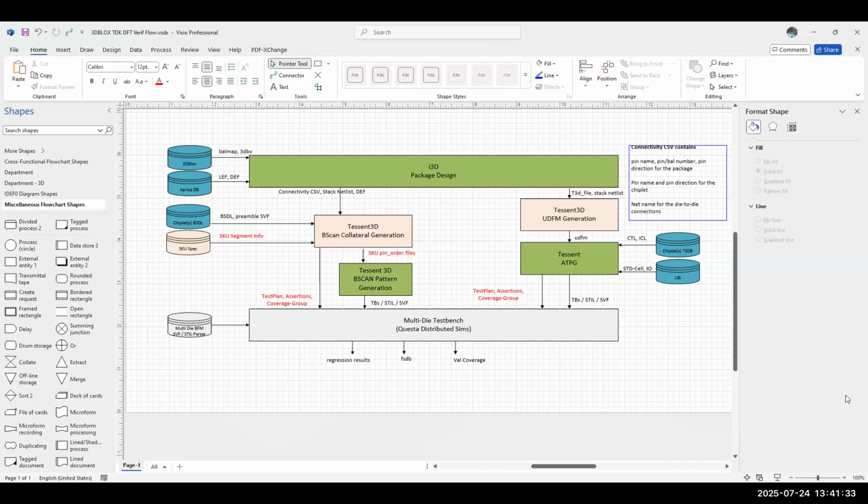Is this the manufacturing fault type testing of the die-to-die interfaces, the stuff that comes out of using the pin locations? Right. So what do we call that format? We call that the placement for our ATPG pattern generation for the inter-die interconnect pins.